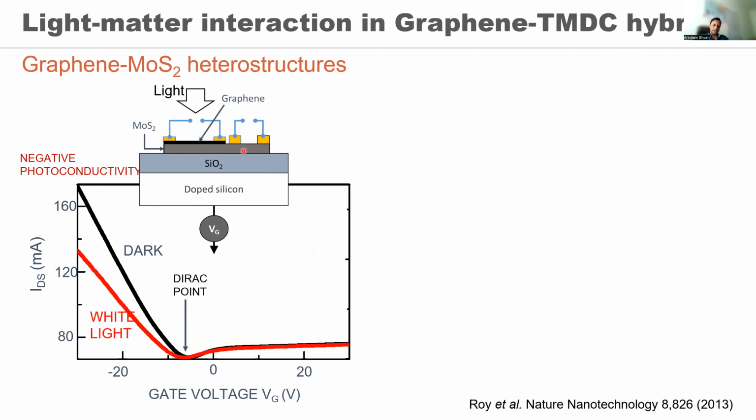You can see the molybdenum disulfide layer here with graphene on top, and electrical contacts on graphene can measure the electrical voltage or current along the graphene layer while it's sitting on molybdenum disulfide. So this is the key feature of such devices. You can see now there's a gate voltage. You apply a gate voltage at the doped silicon underneath. Silicon oxide here acts as a dielectric.